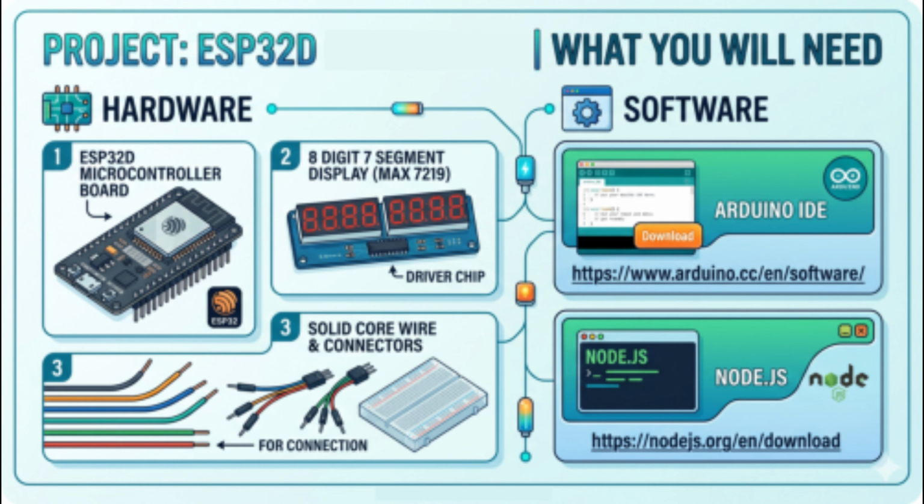Okay, so these are the things you're going to need for this project. On the hardware side of things, an ESP32 microcontroller board, and an 8-digit 7-segment display using the MAX7219 driver, which makes it really easy to program. And we're just going to need 5 wires to connect these two things together. On the software side, we're going to need the Arduino IDE to send the instructions to the ESP32 controller board, and Node.js. This is the runtime which is going to run our little program which streams the data from Microsoft Flight Simulator to our microcontroller.